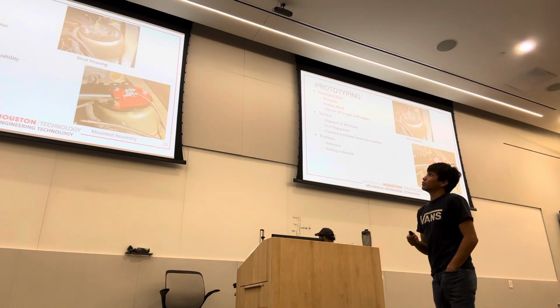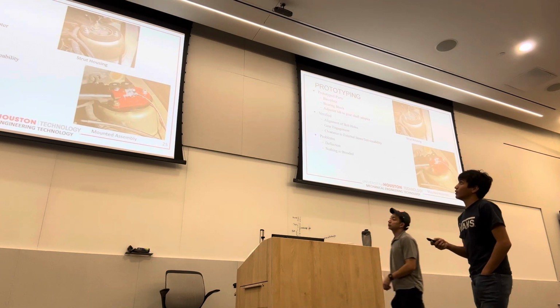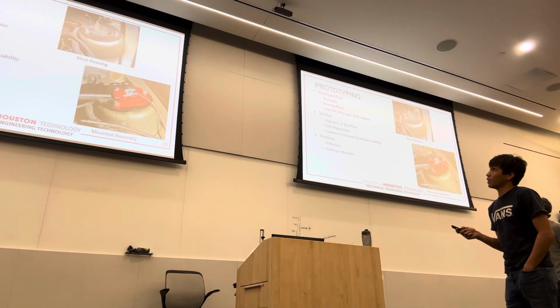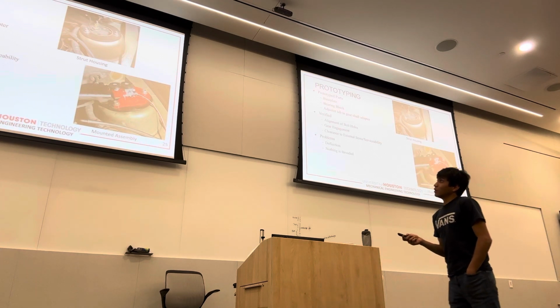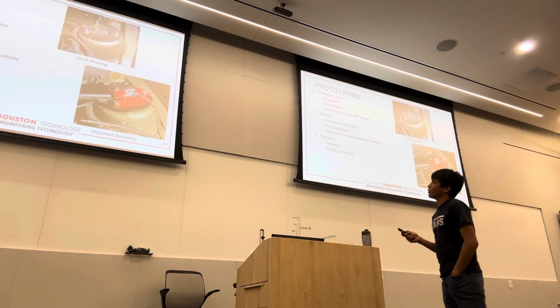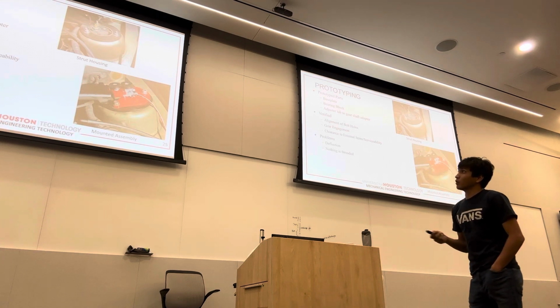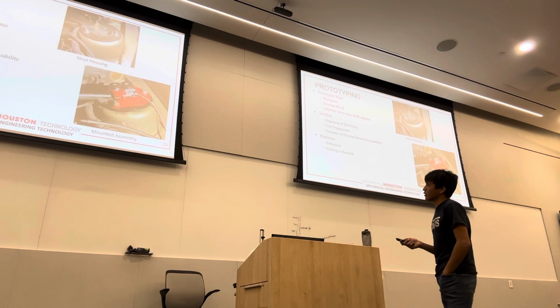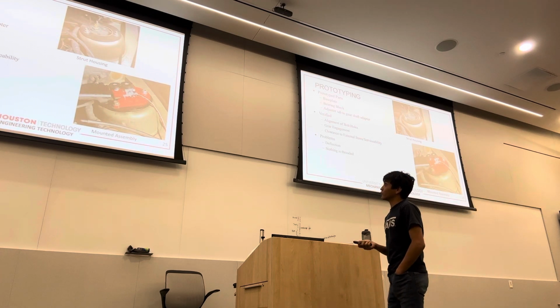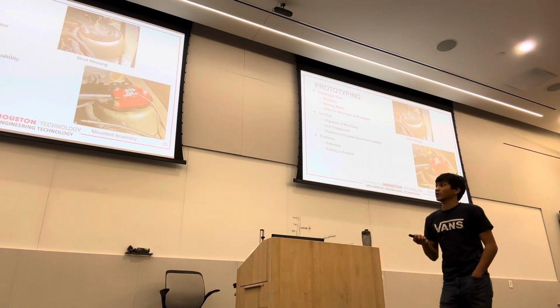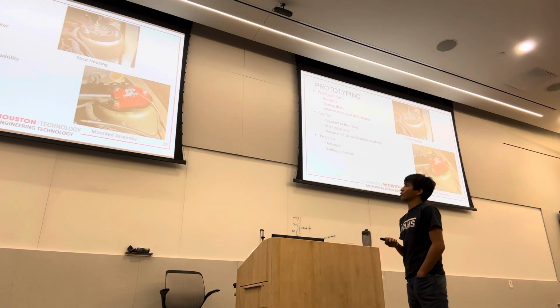Prototyping. The parts we needed to prototype to make sure they fit were the base plate, the bearing block, the adjuster tab, and the gear shaft adapter. We prototyped these as 3D printed parts, and everything looked good. We got good alignment of the bolt holes and the gear engagement, and it's fairly serviceable. Since it was all plastic, the biggest problem so far was deflection, and nothing was threaded. So it wasn't that permanent, of course, so we wanted to move to metal.